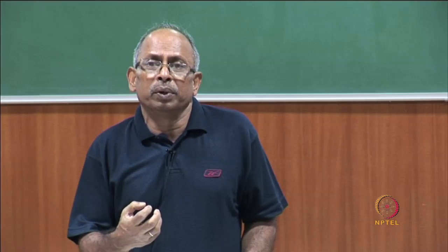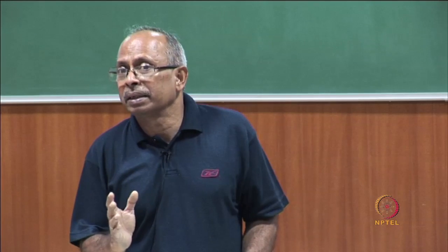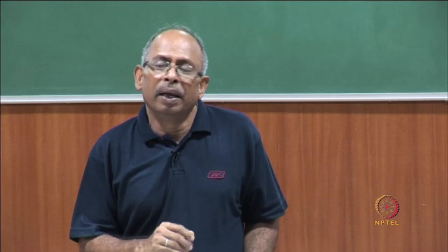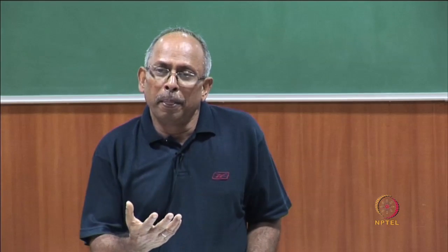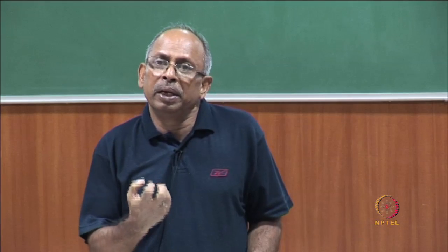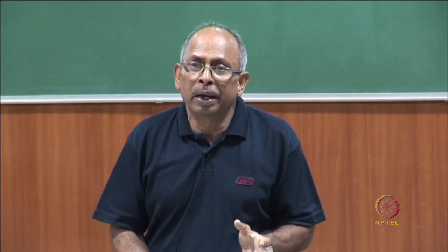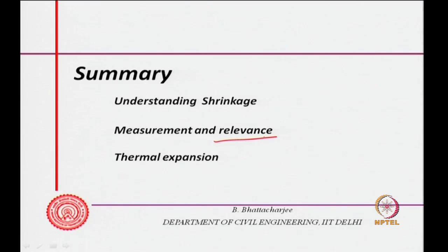Of course, the tensile strength of a dry specimen is more, because there will be no shrinkage cracks. We talked about that earlier, and then we looked into various measurement methods and the relevance of shrinkage in cracking. We tried to look into types of cracks, and lastly we looked into thermal expansion of concrete systems and the factors that affect it.